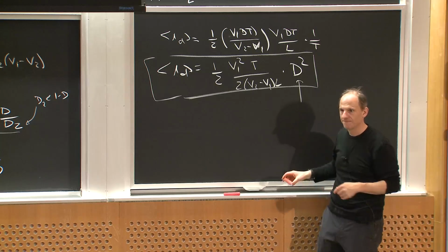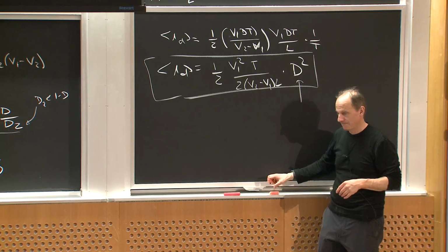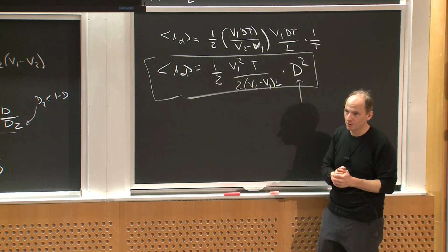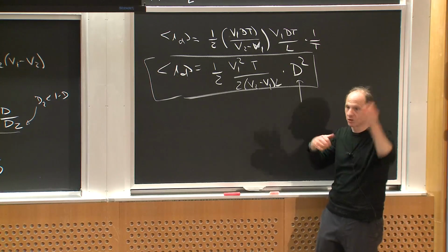Okay? Yeah. So does that mean when you go from CCM to DCM, you're probably going to change the duty cycle to maintain a target voltage? That's right. You're going to use a lower duty cycle than you would otherwise use in the boost converter. Yes. That's right, because the conversion ratio goes up.